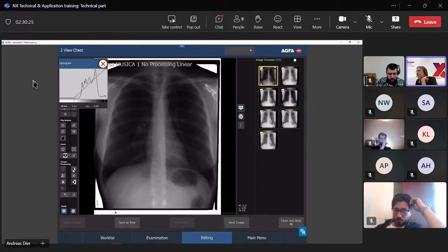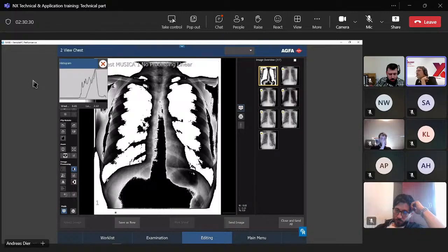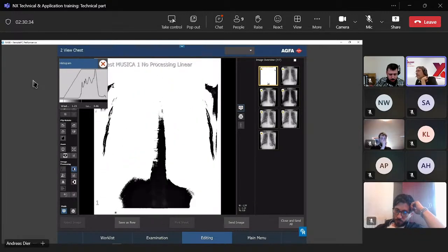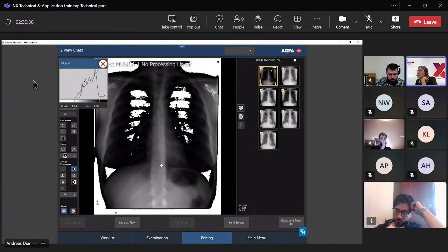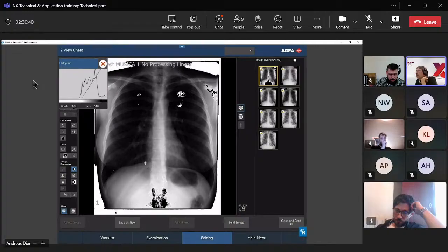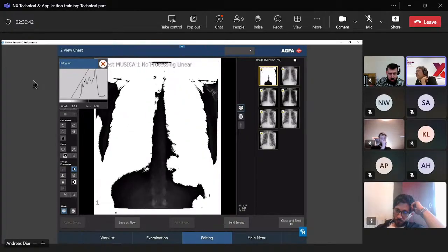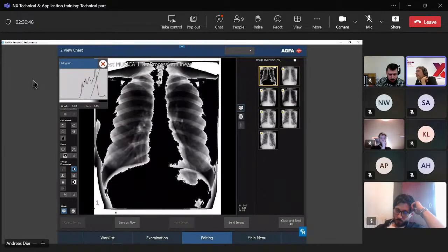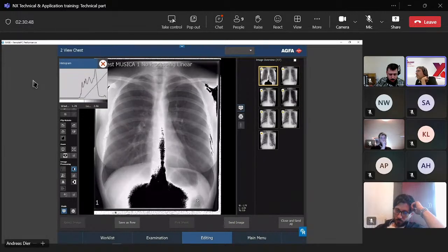And if you use the window level function, the burn function indicates everything that is in clipping by black or white, depending on which side of the histogram we have the clipping, and we can mess the image up completely if we do not know what we are doing.